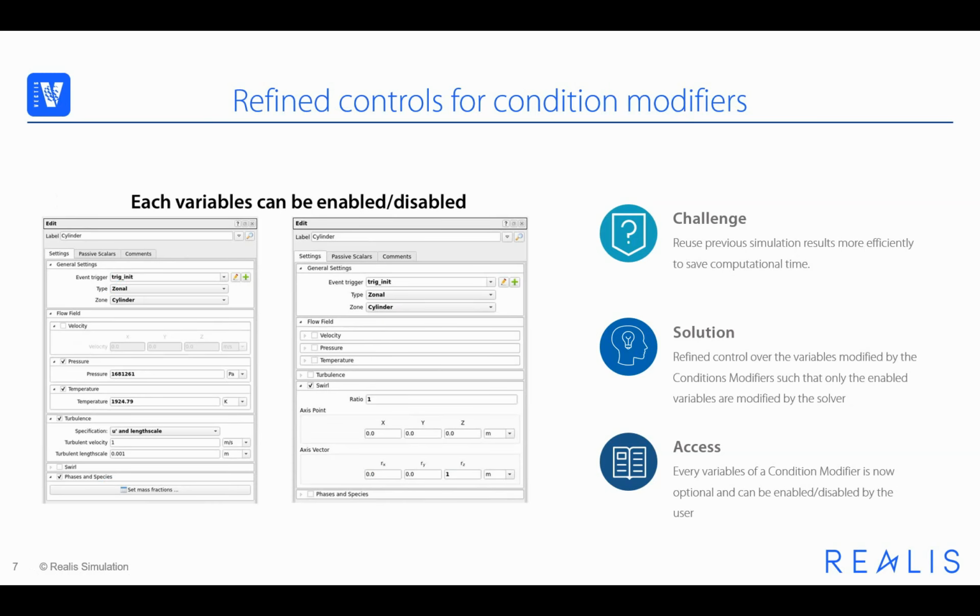The reuse of simulation results is paramount to the efficiency of computational workflows. From the calibration of engine results, spray and combustion for example, to the computation of different operating conditions for fluid systems, using a previously converged simulation may significantly reduce the required computational cost of subsequent iterations. Efficiently reusing restart files rests on the possibility of selectively modifying the flow field as required by the new calculation.